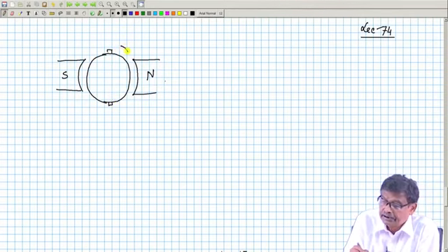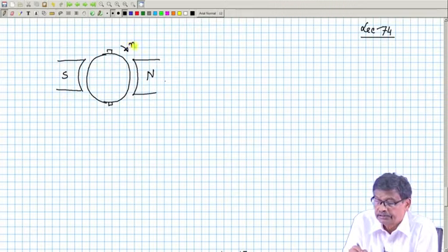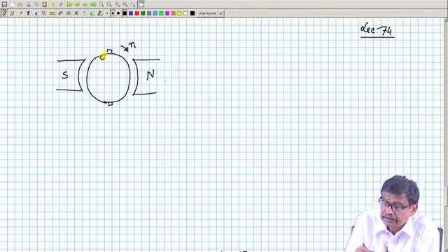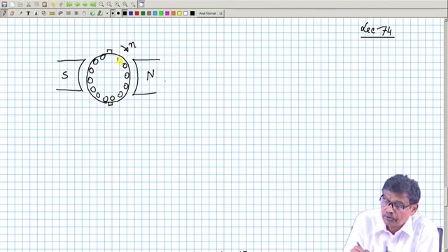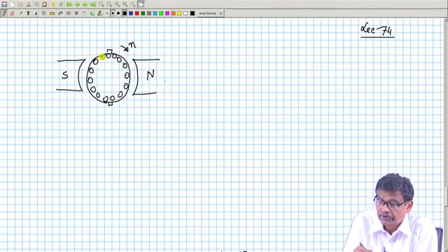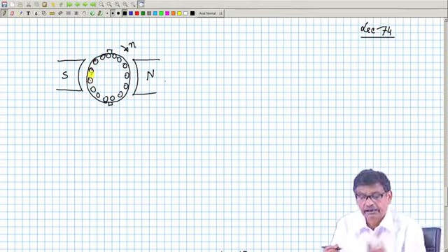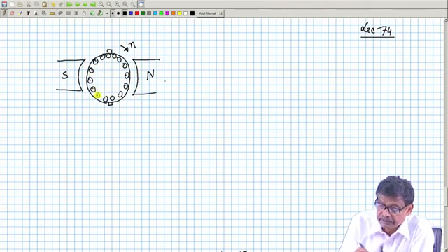If the generator direction of rotation is like this, then these conductors will have induced voltage as well as direction of current. Under the south pole, it will be all dot, so that the electromagnetic torque becomes opposite to the prime mover torque, and these are cross. This is what we have seen. Clear? Generator mode.